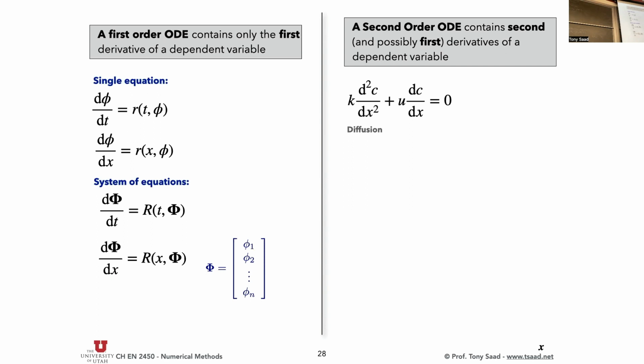So if you heat one end of the rod, those molecules at the end are going to get super hyperactive, and then they're going to push that excitement all the way through the rod to the other molecules. So that's diffusion. And it's always associated with the second derivative. Okay, once you take heat transfer and mass transfer, you will learn Fick's law and Fourier's law of diffusion, right? It's always a second derivative, okay? That is describing that process of communicating information at the molecular level.